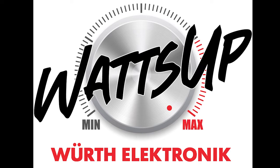This leads to our first design tip: find suitable core materials. For switching frequencies under 100 kilohertz, you should use iron powder, ferrite, superflux. And from Worth Electronic, the PERM series is suitable. For a switching frequency between 100 and 1000 kilohertz, you could use ferrite, superflux, and again, the PERM series. And finally, for a switching frequency of greater than 1000 kilohertz, it's best to use ferrite. The PERM is suitable for all three types of switching frequencies.